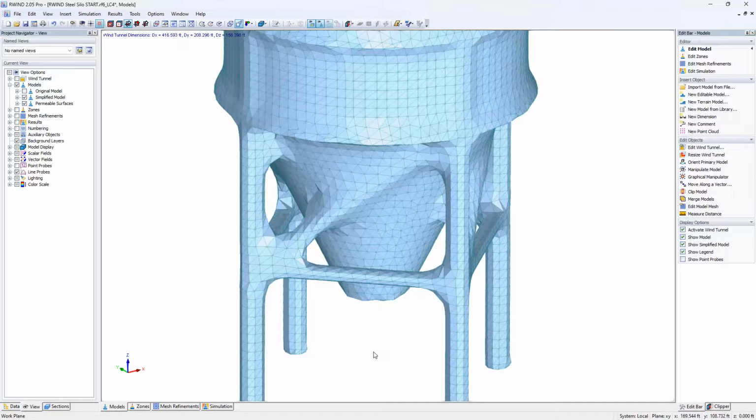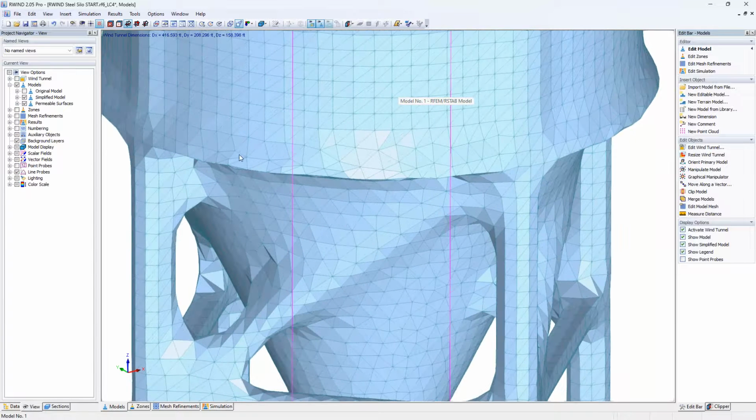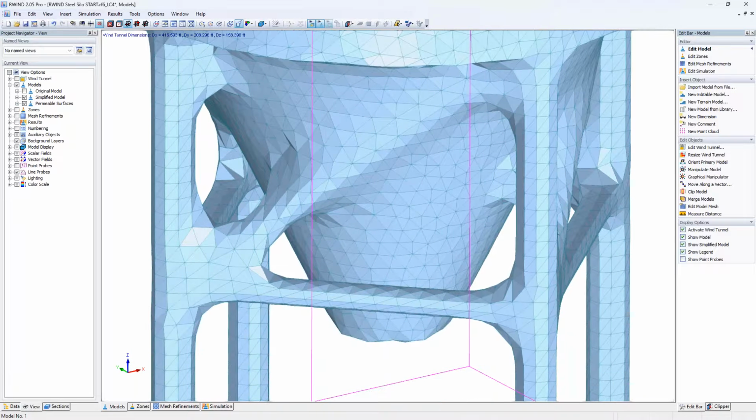And again, it's needed in that CFD calculation with that OpenFOAM solver. It's also correcting any mesh errors automatically. So you'll notice that if we zoom in here, we have triangles everywhere that have to intersect perfectly with the adjacent triangle. So the program has taken care of all of that for us. It has closed a lot of these open edges.